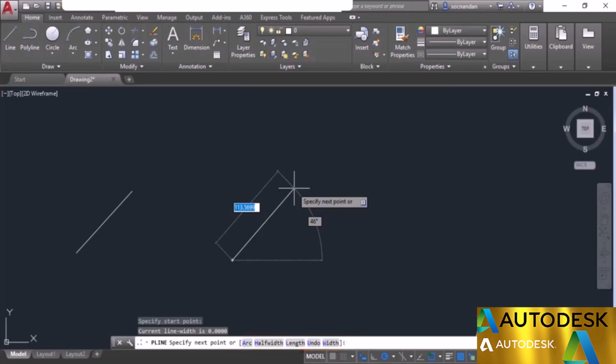Now these options are also available on the dynamic input, and you can access these options simply by pressing this down pointing arrow. So click on this down pointing arrow as mentioned on this tooltip also here. So click on it, and now all those options are available as a list. Now you can simply keep pressing that down pointing arrow, or you can also press the up arrow and choose the desired value. So I'll select this width option and now press enter.